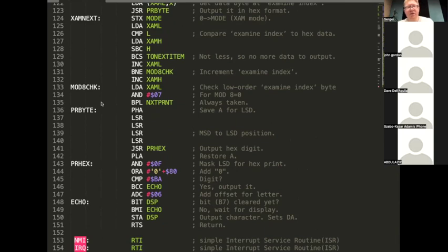Chars are encoded by ASCII code, and ASCII code should be sent to a display, and vice versa. If we read something from the keyboard, for example 9, in hex it would be 39 in ASCII code, and then we need to convert it to the real 9, so we need to subtract 30, and so on.